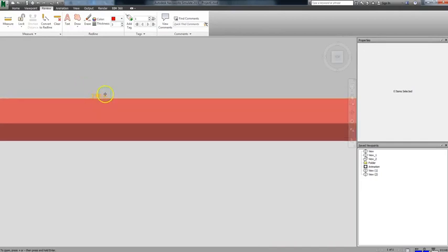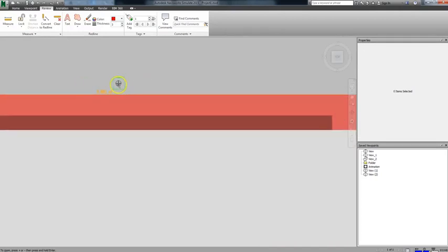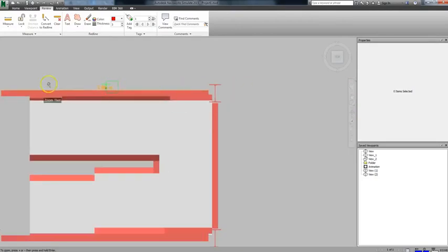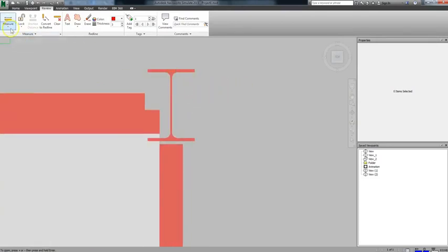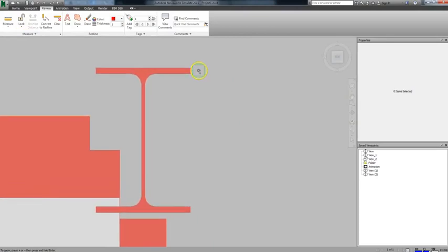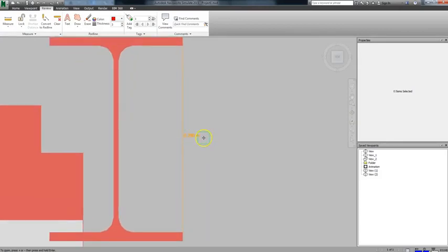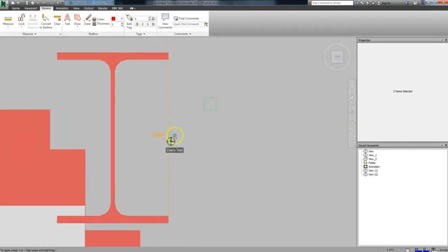If you zoom out now, you'll be able to see the measurement of that length of the beam sitting right above it. Alright, so let's try another one. You can take measurements between any two concrete distances in Navisworks. So we can even do it from this beam that runs perpendicular. Just make your connection between the 2 points, left click, and it's there. You can use the point-to-point measuring tool to measure the distance between any two objects anywhere in your project.